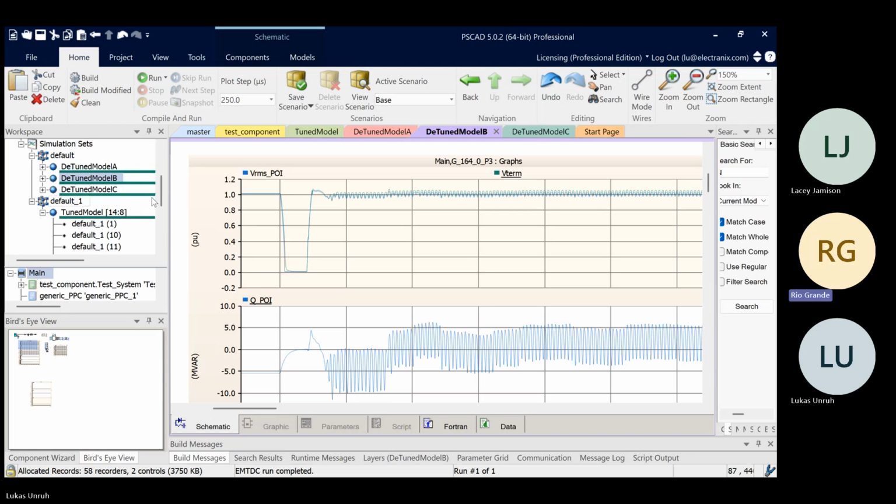Also, a warning for some folks who are system operators: once you change something, say you know it's a time constant in a generic model because you've seen it before, and I change it and get it to work, then it's not the plant model I was given. So that's another reason not to fix it yourself. You can, but just send it back for confirmation.